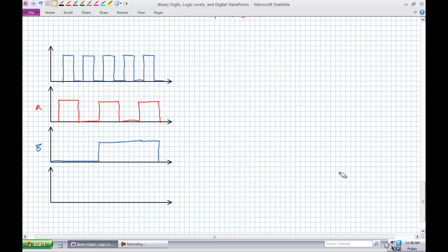The next thing I'd like to introduce in this lecture is something very critical to your understanding of later concepts of digital electronics, and that is what's known as the timing diagram. Timing diagrams are kind of like an oscilloscope. They are a time representation of a number of digital waveforms displayed on a graph. Think about multi-instrumental sheet music: you're trying to figure out who's playing what at a specific time. So you display signal A in red and signal B in blue in relation to each other. At a specific time, what is the value of A compared to the value of B, and vice versa?